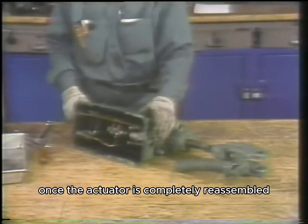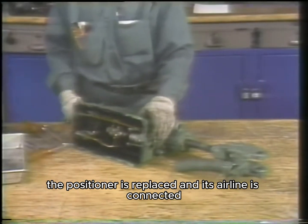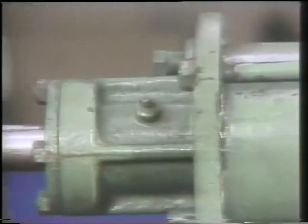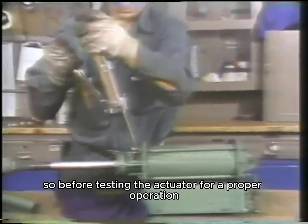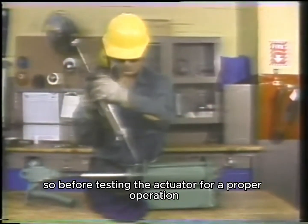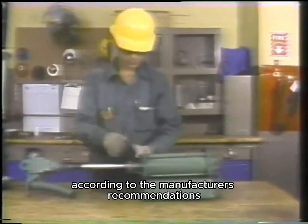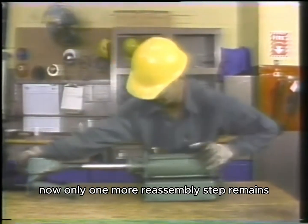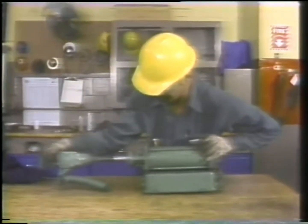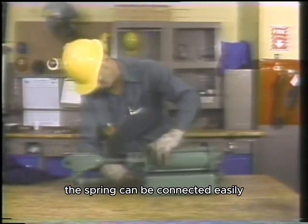Once the actuator is completely reassembled, the positioner is replaced and its air line is connected. This end cap is equipped with a grease fitting, so before testing the actuator for proper operation, the technician greases the unit according to the manufacturer's recommendations. Now only one more reassembly step remains, attaching the feedback spring. Once the piston rod is fully retracted, the spring can be connected easily.